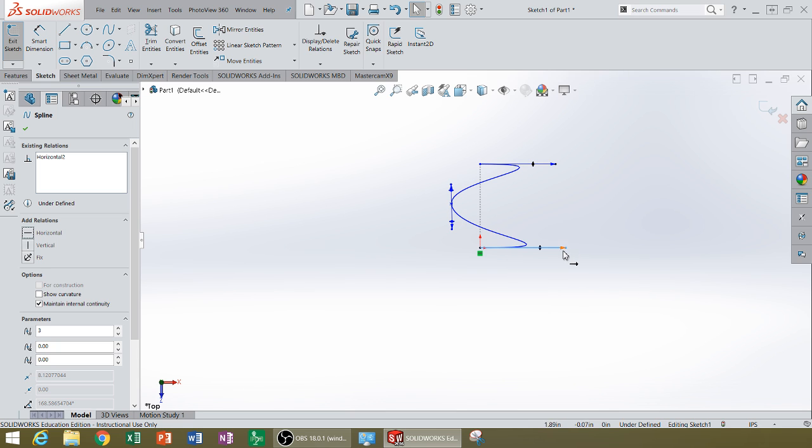Now what I've done is given them an association so they move together, and you can see they're still not the same size. I could bias one more than the other. So now we can start to associate the size of these handles and look at the relationship. As I move my handle that associates with the top point, my top handle gets longer and my bottom one gets shorter. So I'm biasing the tangency or the handle on it.